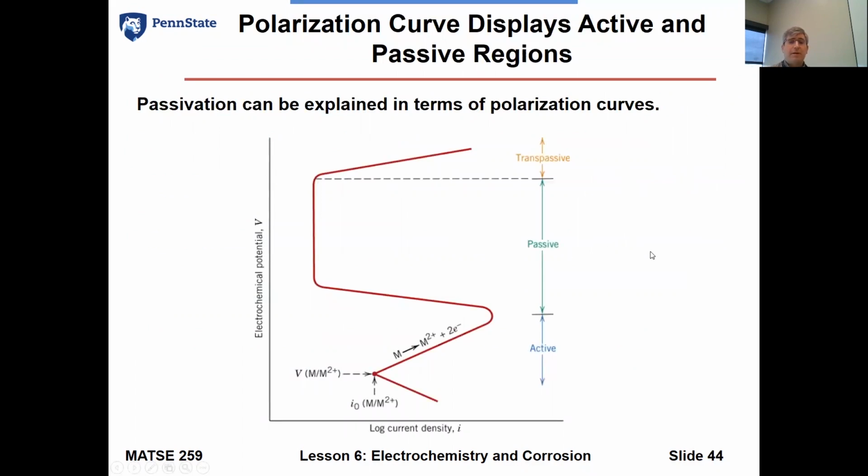Now, we talked about polarization curves the last time. What we saw was the activation polarization. If we were to look at corrosion as that electrochemical problem that we've been talking about, we need to look at current density because we know there's electron transfer between the anode and the cathode, and we can drive that by changing the potential, or that pressure, very much like you might remember from your physics classes talking about the basics of electricity, Ohm's law, V equals IR. In corrosion, we do a lot of the same things where we'll vary the potential and look at what the impact on the current density is. So what we'll try to do is drive the corrosion process.